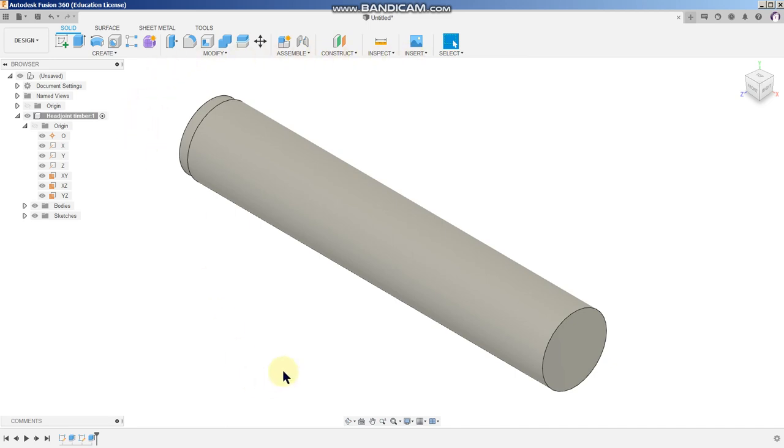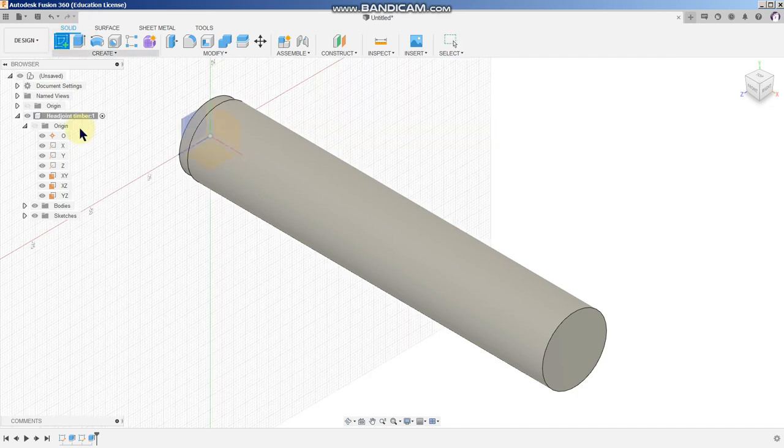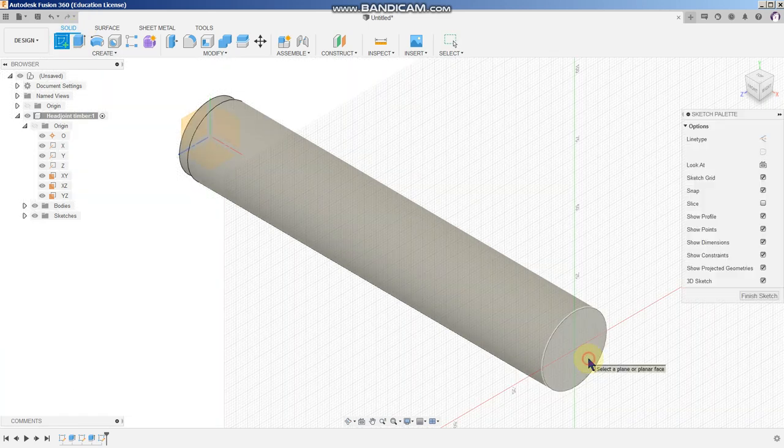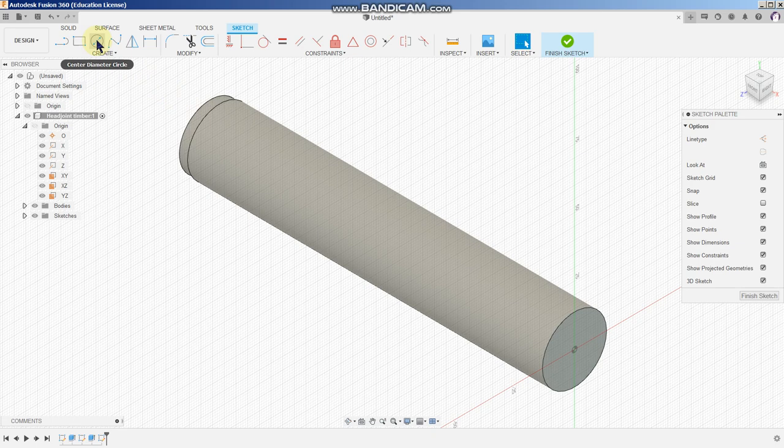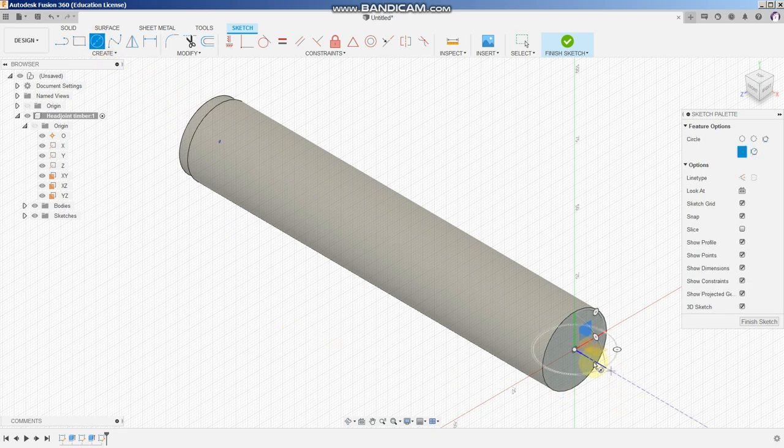Now I need another 4 millimeters just there, so I create a sketch, create a circle. Doing it like this without looking at can cause you all sorts of problems if you don't put the cursor exactly at the center. And we want that to be 26.5.